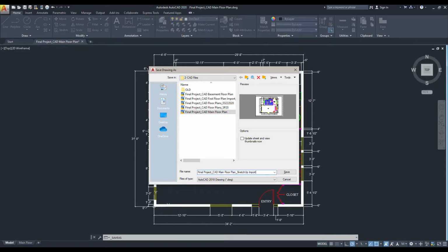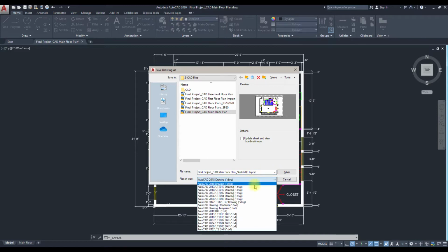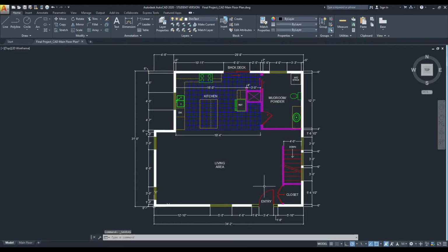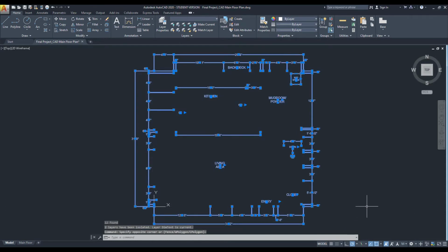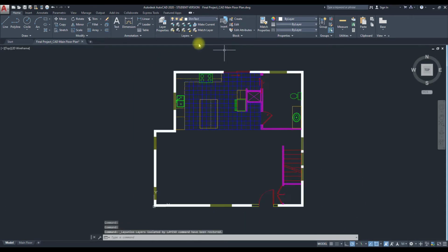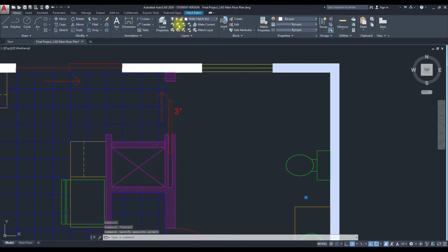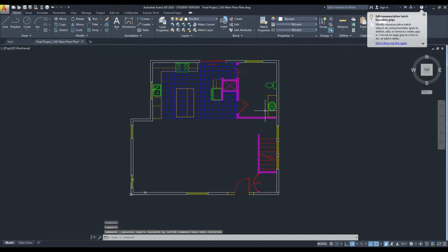If the import to SketchUp does not work, you might have to save down the CAD file to a version a few years older, such as 2010. In your newly resaved CAD file, simplify the drawing so it does not take too long to import. Delete layers and the objects on them you will not need, such as schedule tables and hatching. Delete or explode unneeded blocks. Delete text and dimensions. SketchUp will not import text and numbers, including dimensions, so this just slows down the import process. Purge the drawing of all these changes.